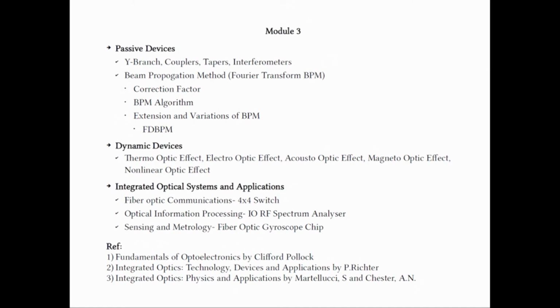So, it is also possible to create devices for many applications like metrology. For example, if you have an array of fiber Bragg gratings and the signal coming from different sensors is to be analyzed, it is possible to analyze by using these integrated optical techniques by creating gratings and other components on the same chip.